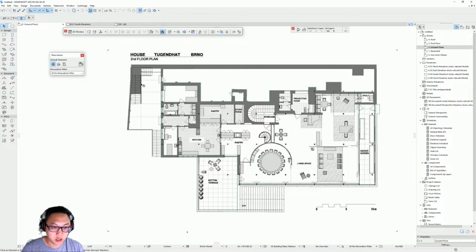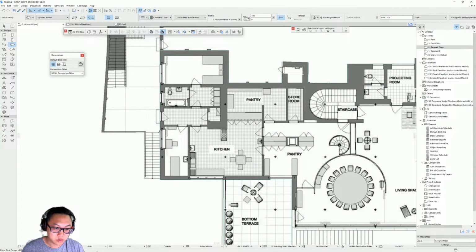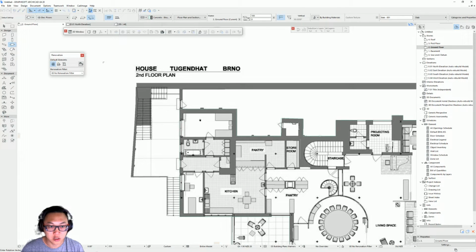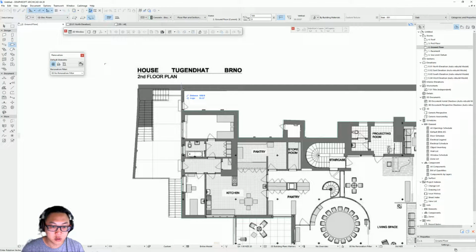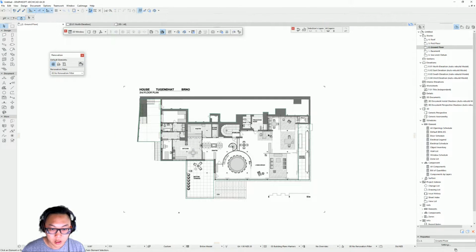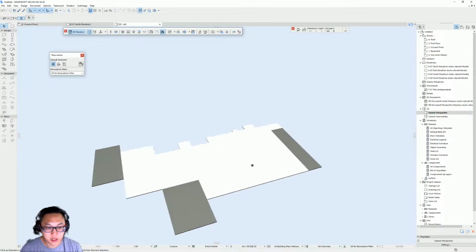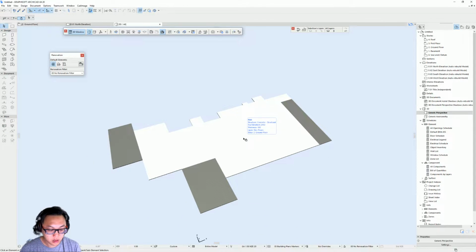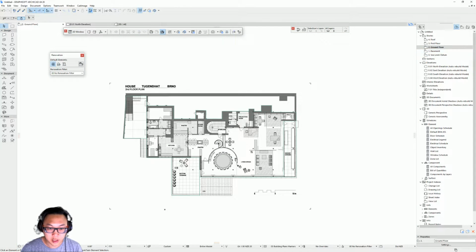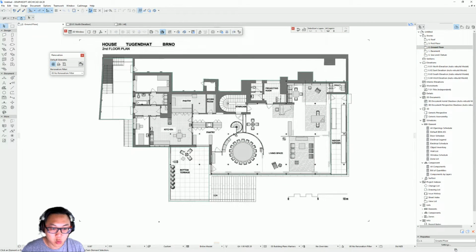And maybe I'm gonna quickly do this one as well. So the same thing, I'm just going to use the syringe tool to go back to the slab tool, and I'm just gonna pull that up. And here I'm gonna select the corner, this little point, and I can just move it around to follow the shape of the terrace. Okay, that's what we got so far. If I press here, I'm going back here, and now we're gonna do the walls.